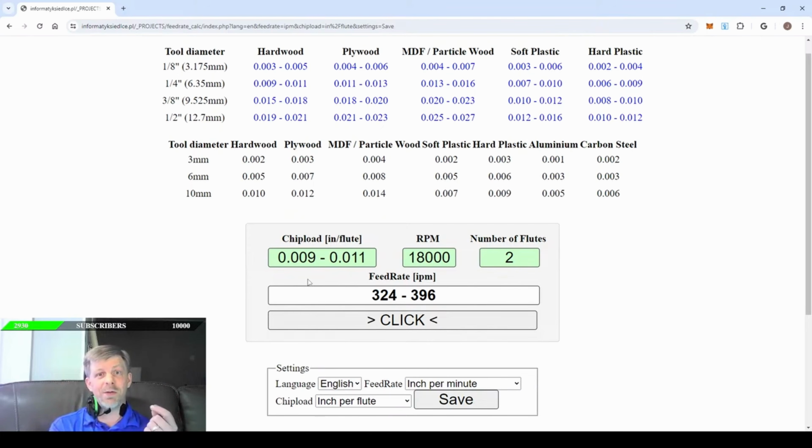And the difference between having a good chip load and a bad chip load is the difference between having less chip out, cleaner cuts, and longer lasting bits. So this is a great thing for beginners: when you first get a machine, the first thing you could do is test what type of wood you're cutting and what the best settings for that cut are. You're simply looking for the coolest bit temperatures.